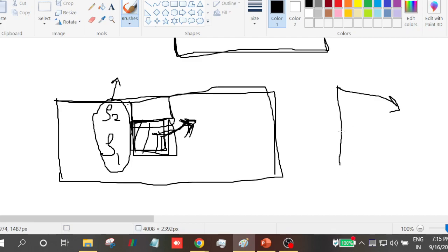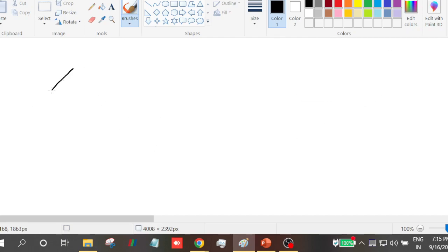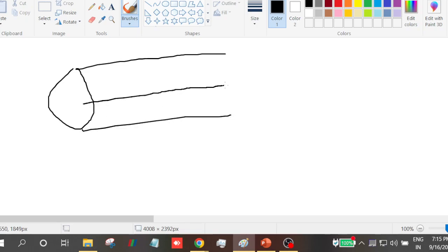That is, if we take a tube, with this top wall, bottom wall, and side wall, when the fluid enters from the inlet, it tries to move to the center from all the directions, even from the top and bottom wall and even from the side walls. So that is why the flow becomes three-dimensional in nature.